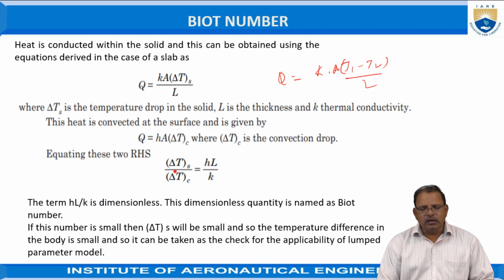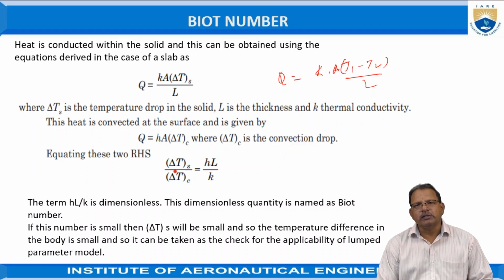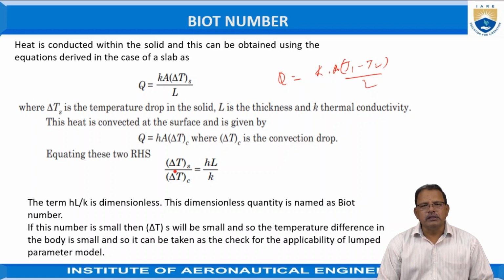This is the heat transfer from one point within the solid to another point in the same object, or between two solids in contact with each other, where Q is the flow rate, the magnitude of heat transferred, k is the thermal conductivity of the material, A is the cross-sectional area, T1 is the initial temperature, and T2 is the temperature at the second point, where L is the distance between the two points at which the heat transfer is taking place.